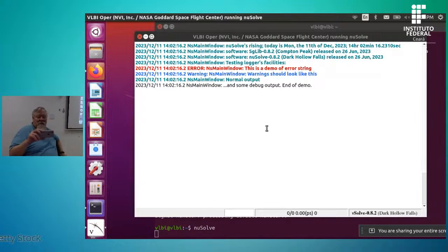Sorry, excuse me. There's an online question that asks, in which place are the station coordinates determined in the focus? The answer is, most antennas have two axes, one that rotates like this, and another that rotates like this. So this is the elevation, then you have the azimuth. And these two axes actually have an intersection.